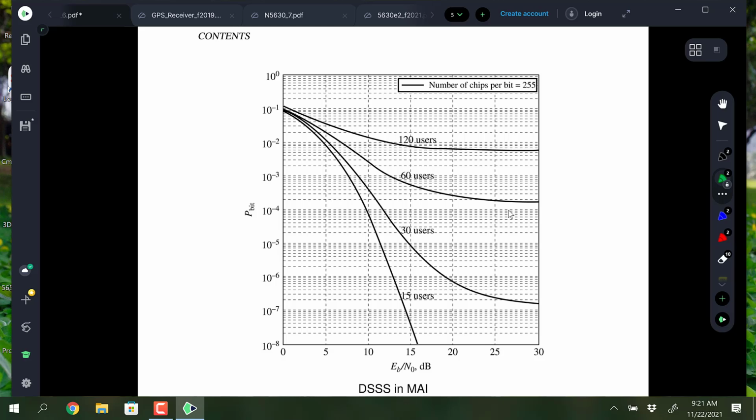There was a power control issue where usually at noontime when people were out going to lunch maybe, or in the morning when people were going to work, this cell site had a problem with power control in that a strong user would come on and it would swamp out everything, and other people could not get their calls set up. And the conclusion to that was not conclusive, but I remember I sat with a spectrum analyzer hooked up to the base station equipment.